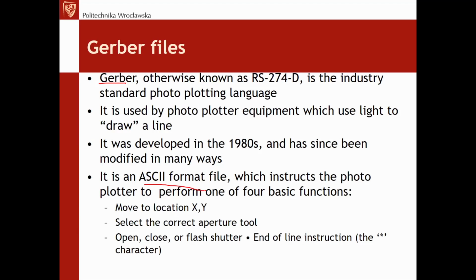Even though these are text files, because they are graphic and they are just coordinates and the tools used, the project which takes megabytes on the hard disk drive during the design phase, after generating Gerber files usually goes into kilobytes, and after zipping or RARing, it's quite often single kilobytes, because ASCII files compress very well.